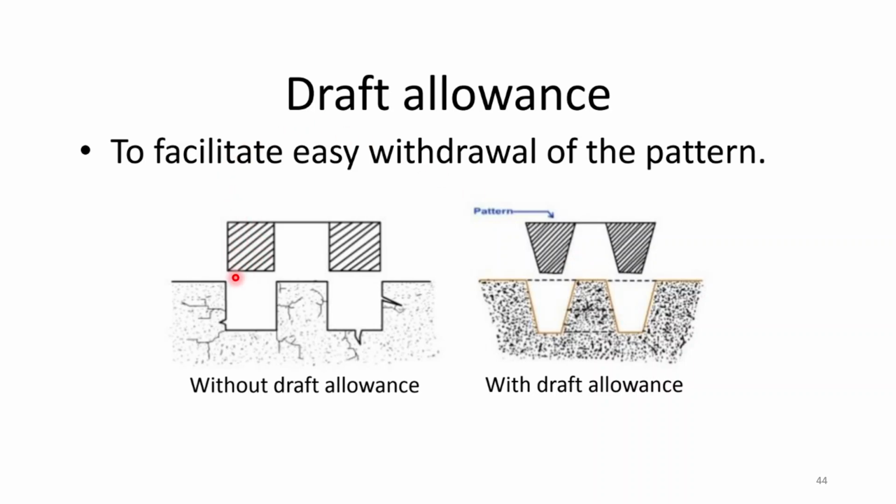That's why there will be more tear in this type of shape. So tapered casting is preferred. After casting this, if you require a cuboid shape, then you will be machining. One second, let me use the pointer. You'll be cutting off this much part to get your final cuboid shape. So draft is required when you have chances of this tear in case of sand.